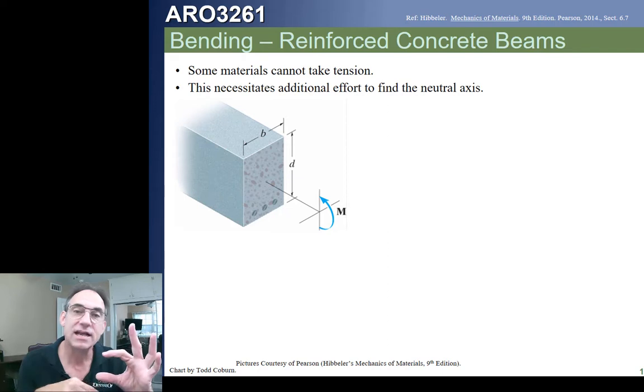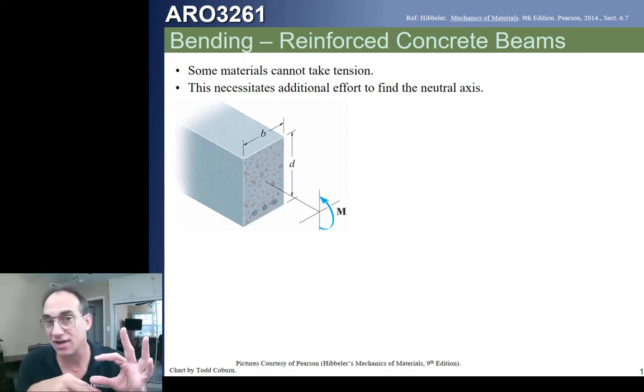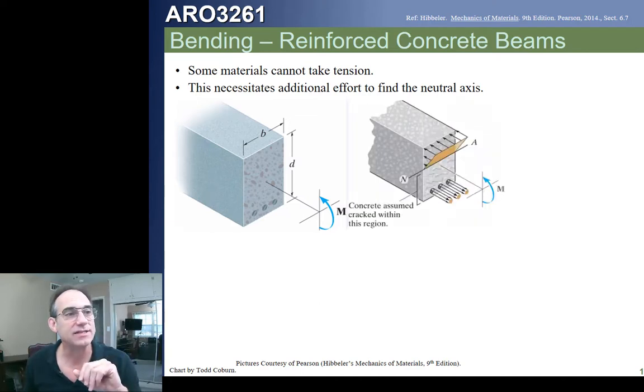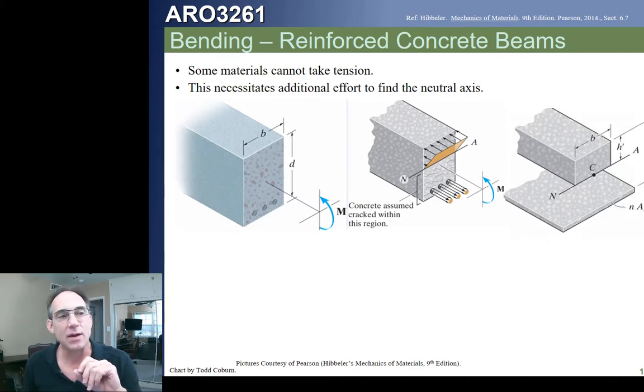What this means is the neutral axis of this section is unknown. So we're going to need a more detailed approach to calculate this. What we're going to do is take the whole part that's in compression and the part that's in tension, and balance those two areas. If we did that, we develop this nomenclature here, where D is the total depth of the section.